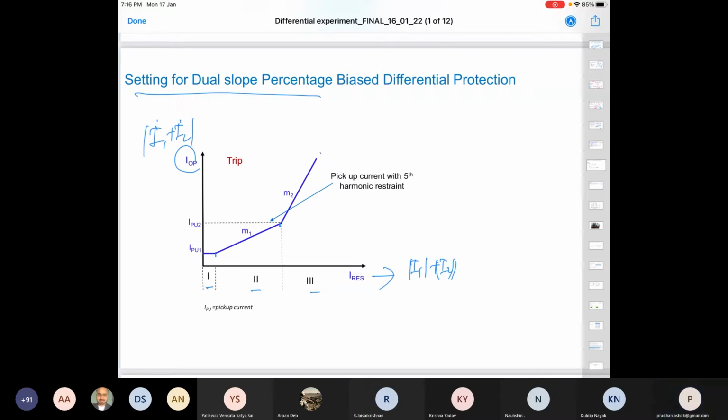So this starting point is the peak of current. Typically this is 20%, 0.2 or 0.25, 0.2 to 0.3 of rated normal current. Rated current, I can say, rated current. Nominal current we call it. Nominal current also, or the rated current, of the transformer.